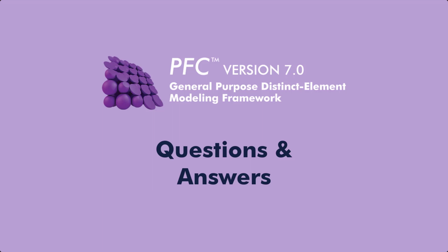Sure, I can speak to that. Yes, I agree that heterogeneity in bonded materials often leads to stress heterogeneity. So heterogeneity in elastic response or in packing leads to stress heterogeneity. And in a lot of cases for discrete systems, we think this is what causes it to be a discrete system. Well, the thing is that the power of this model, in my opinion, and this is highlighted in Leandro's work as well, is that if you pack up balls, you put a stress state in,